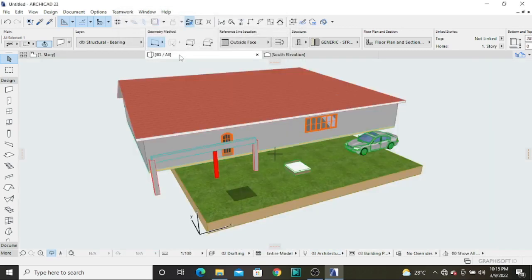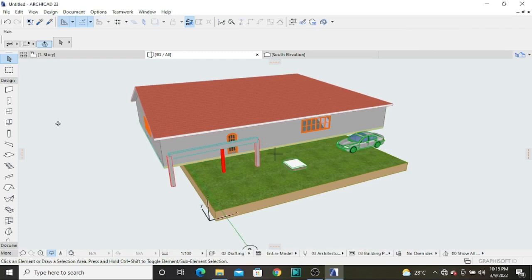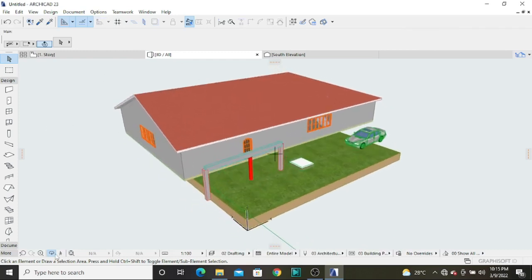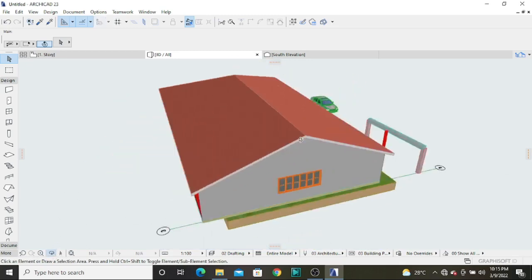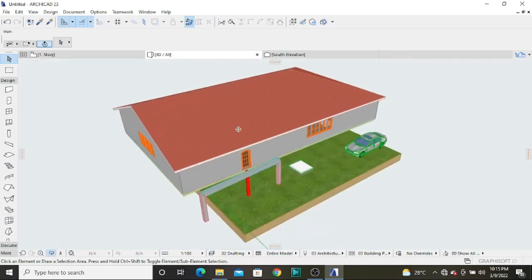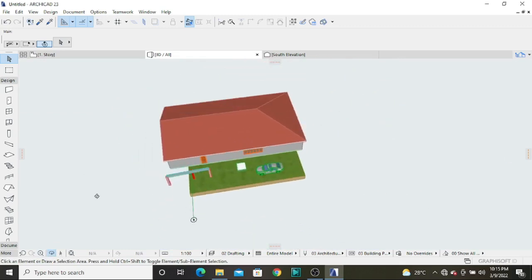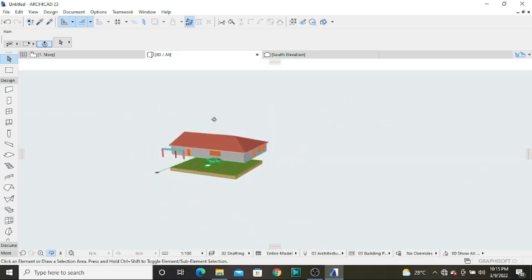We also have a 3D window. This is used whenever you want to insert 3Ds. You can orbit, which is changed down here. You can disable that. You see you cannot orbit anymore, but once you enable that, you can orbit your drawing. And also there is a keyboard shortcut for that, which is Ctrl O.